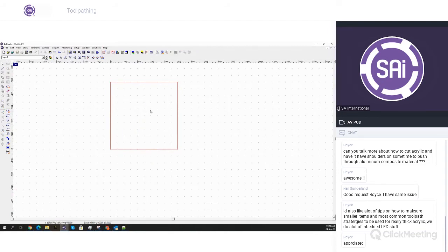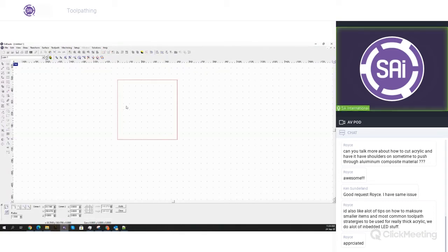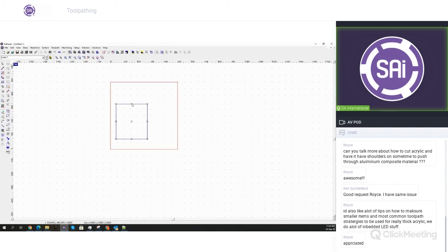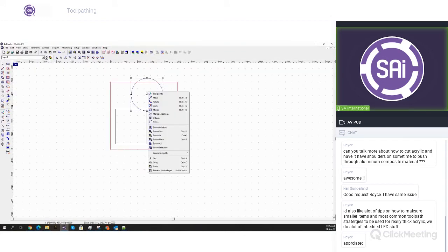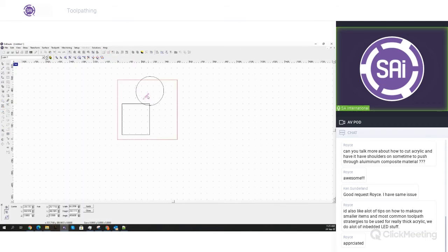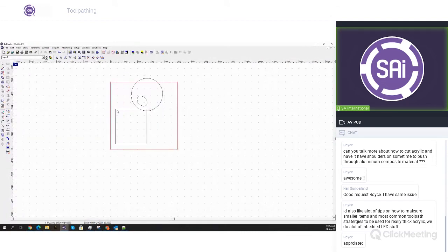So I believe now we've covered everything from the routing offset. So we can go forward with the hatch fill and the island fill. Typically a hatch fill would be used to route out large squared pieces, I would say. If you go more into an oval one, or if you have an object which has a lot of pieces in there or letters, then you would, for example, go for the island fill.